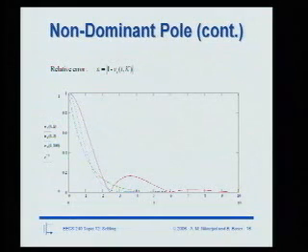Yeah, I guess the time constant depends on a lot of process issues, so it's not a fixed value. Yeah, I mean, maybe that would be a good master's project, to find a circuit that has a clock that varies with the time constant of your system, and then you could clock it so, boom, over process and temperature, you're always stopping at this point, and you're saving yourself a few time constants. Well, it's probably not worthwhile, right? It's a pretty complicated circuit to even think about. Might as well just wait 5 or 6 time constants, and you're good to go.